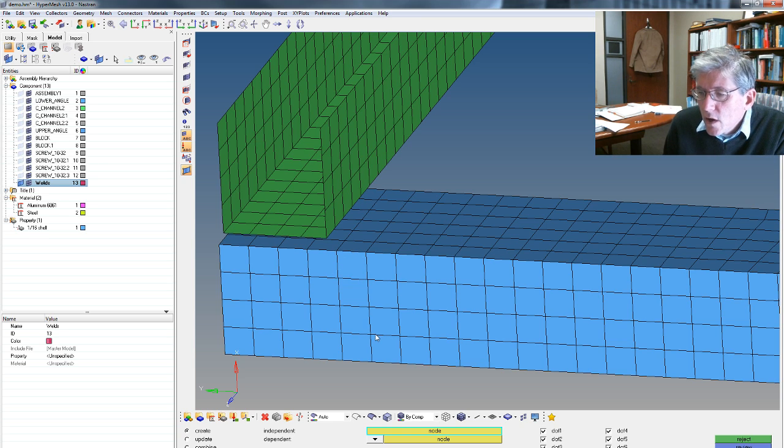So we can go from channel to angle or angle to channel. It doesn't matter. It's a good idea to kind of keep them consistent. And then the mathematics of dependent and independent node won't really become an issue. But let's say we want to do a weld bead, so we maybe want to go from this node to this node, and maybe this node to this node, right? And so now we're adding those rigid connections.